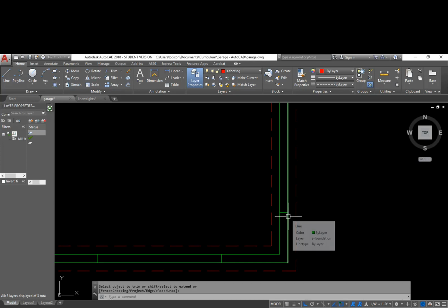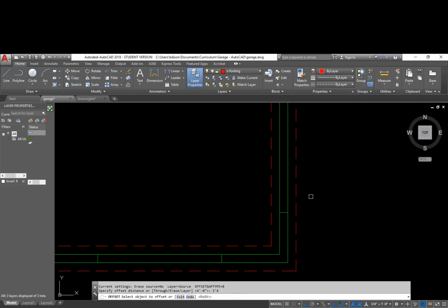So we're going to give ourselves, the frame would typically be a 3/4 inch thick frame, but I can't attach that frame directly to the block easily. So what I'm going to do is I'm going to use some 2x4s in there to build out this frame, and I'm going to use a 3'4" opening for this so that it's modular and I have enough space to add that door in. So I'm going to offset 3 feet 4,